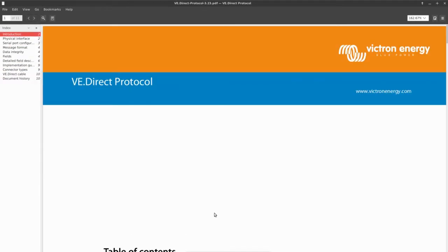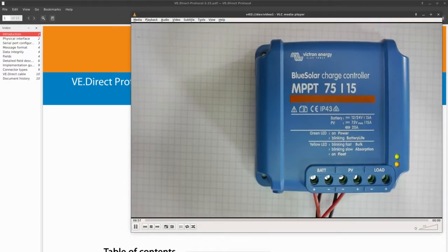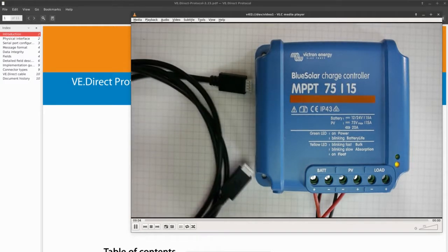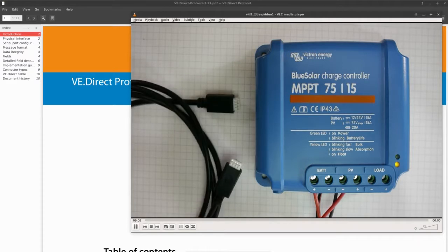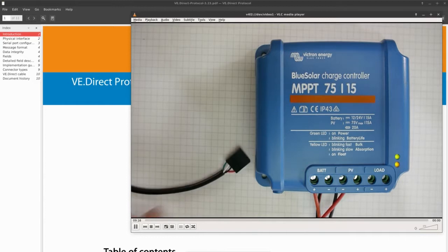as well as the Bluetooth dongle, Victron Energy's cable. There are a number of cables. They've got USB ends, they've got 9-pin serial connectors, RS232 connectors, but I bought this one and chopped it so it had 2 JSTs, and I just put a DuPont on the other side.